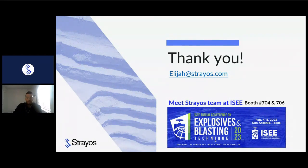Yeah, a typical term is cap rock, we like to say. I've run into it a lot, and I think some good practices I've come across is, depending on what you're loading as primary explosive within your column, as you come into that cap rock, let's say on the top third or 10 feet of your column, maybe using a packaged product, a stick product, or doing a quick deck with maybe a booster to break up that cap rock if it's just a small amount.